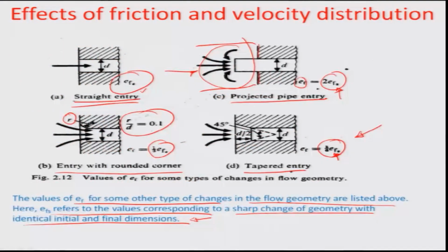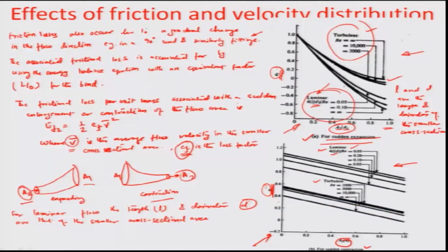and we are also suggesting that the flow in our case is actually a turbulent flow. In the turbulent flow, as we have illustrated here, the Reynolds number is close to about 68,000, which is somewhere in between these two values. One value corresponding to the EF at A2 by A1 equal to 0 happens to be close to about 0.5 and the other one is 0.4. So, somewhere in between, by extrapolation of the EF values,